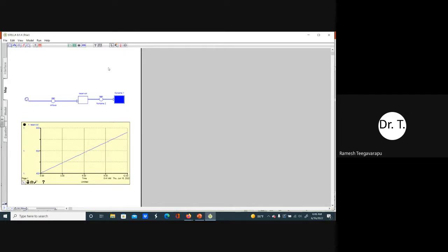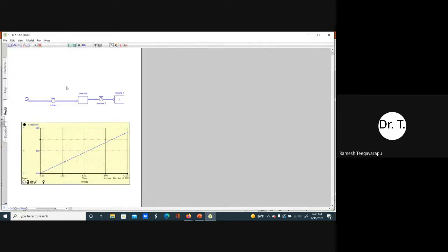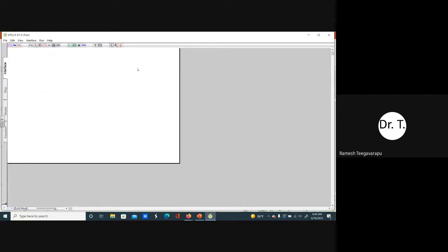Unfortunately, I cannot simulate a lot of scenarios, but the idea is that you have sensitivity analysis and Monte Carlo analysis within this, and you can also look at the equations formed in the background. It's basically solving a finite difference equation for the whole model we have just represented, and that's your model. You can also build your own interfaces, in the sense that on the top you can build, for example, let's say I want to change a factor for the amount of infiltration, right?